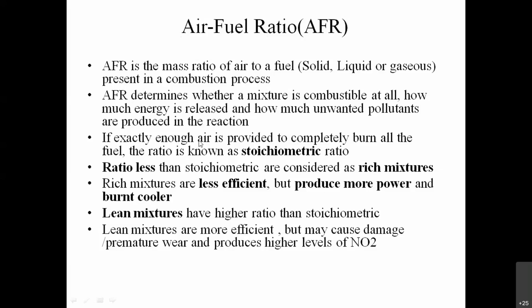If exactly enough air is provided to completely burn the fuel that has been added, that ratio is known as the stoichiometric ratio. It's the ratio of air to fuel which is responsible for completely burning your air and fuel mixture. The ratio which is less than that is known as a rich mixture, and the ratio which is greater than that is known as a lean mixture.